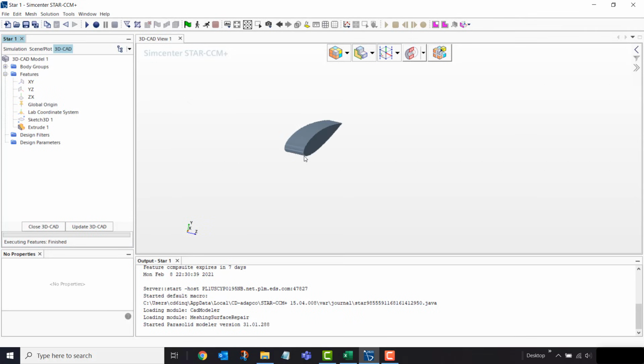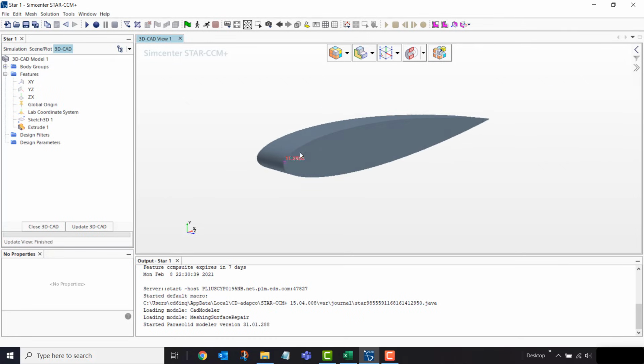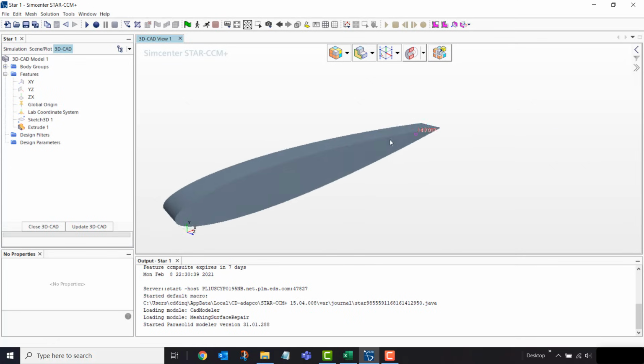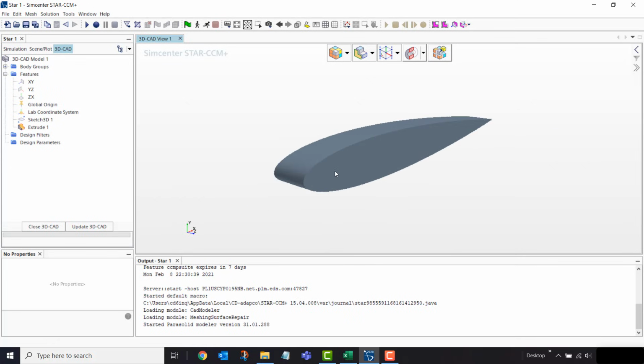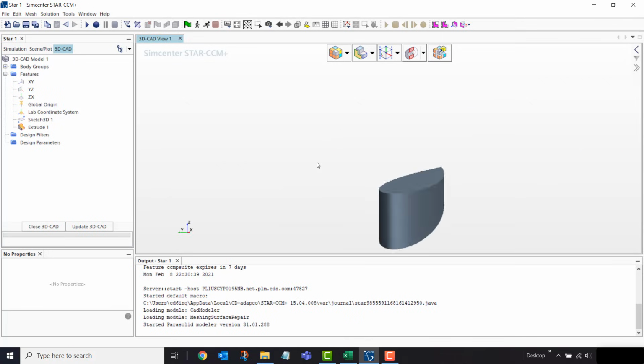Now, some controls for the left mouse button. When you hold that down, you can create a point of revolution about that. So here I'm doing the leading edge. This is the trailing edge down here. Right click is pan, and the middle mouse button is zoom in and out. There's also hotkeys, so if I press T for top, there's F for front, and there's S for side.